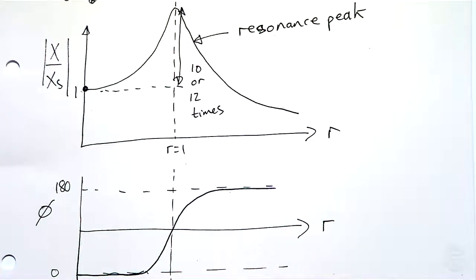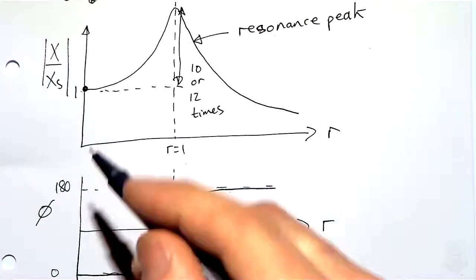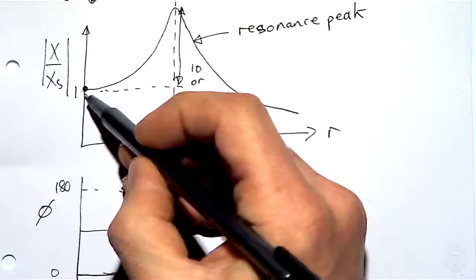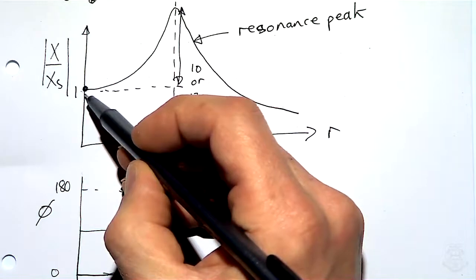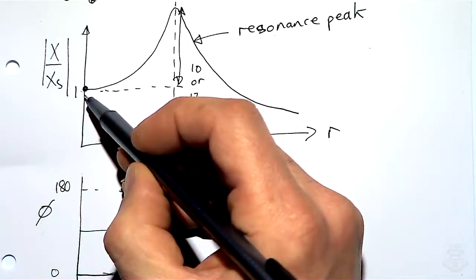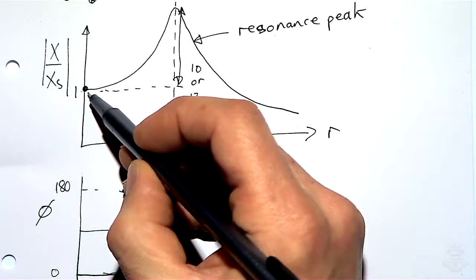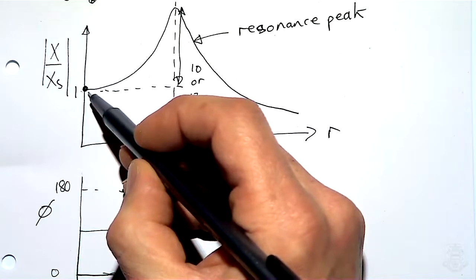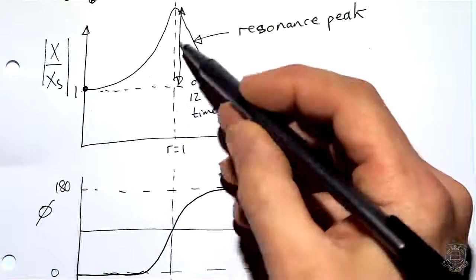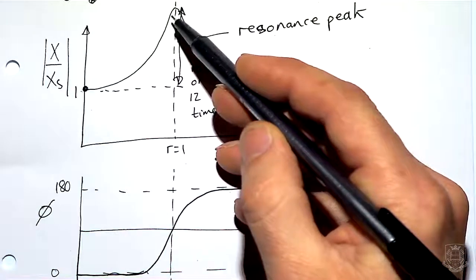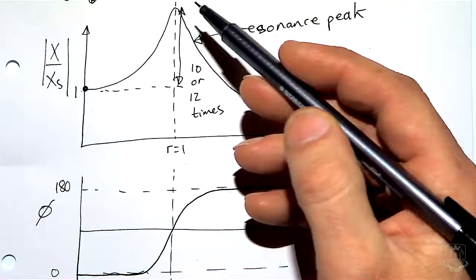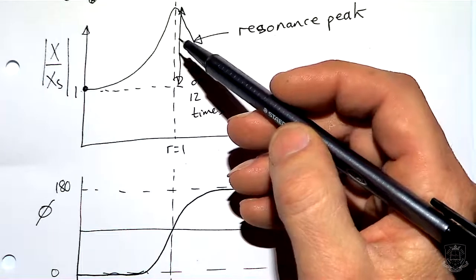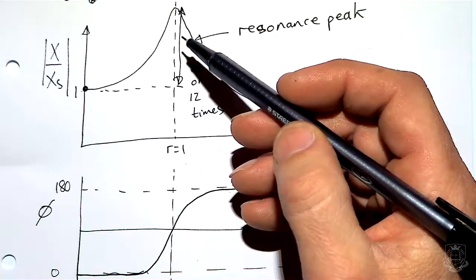So you can see why engineers become worried about vibrations. Because everything you learn in statics, so everything about stress and strain and what you might call static analysis, applies to this case here. So if you're designing your aircraft and all the structural design, you're designing everything to be here. As soon as you add vibrations and you come to a resonant frequency, you have the potential to amplify all of the loads by an order of magnitude at least. So that's why you need to be very cautious.